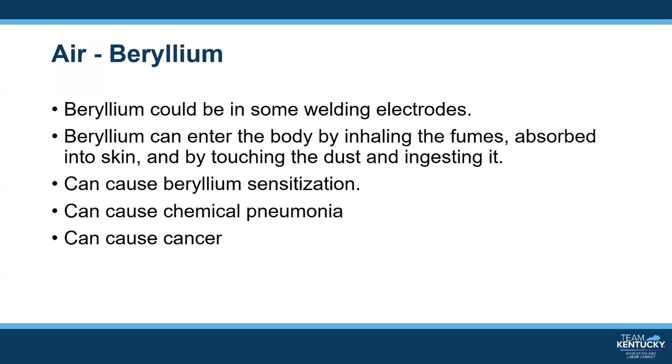Another possible air contaminant could be beryllium. Beryllium can be found in some welding electrodes and some brazing rods. These can be in a combination of other metals mixed with beryllium. These other metals could be things like copper or bronze. Workers in industries where beryllium is present may be exposed to beryllium by inhaling or contacting beryllium dust on surfaces.